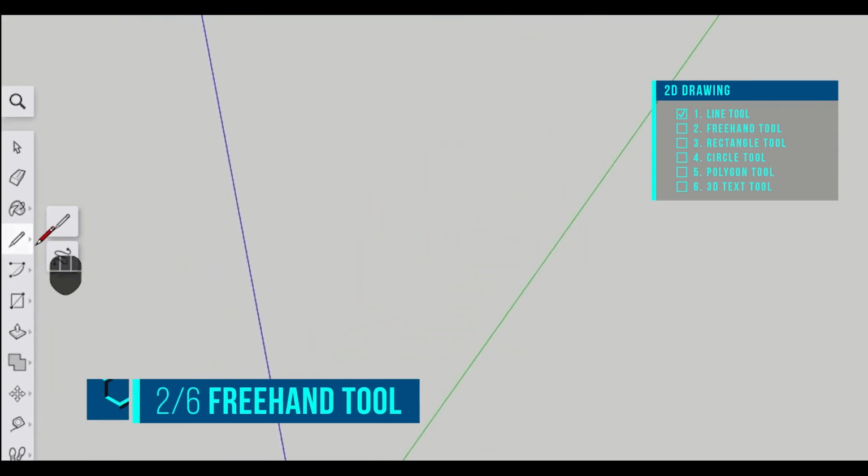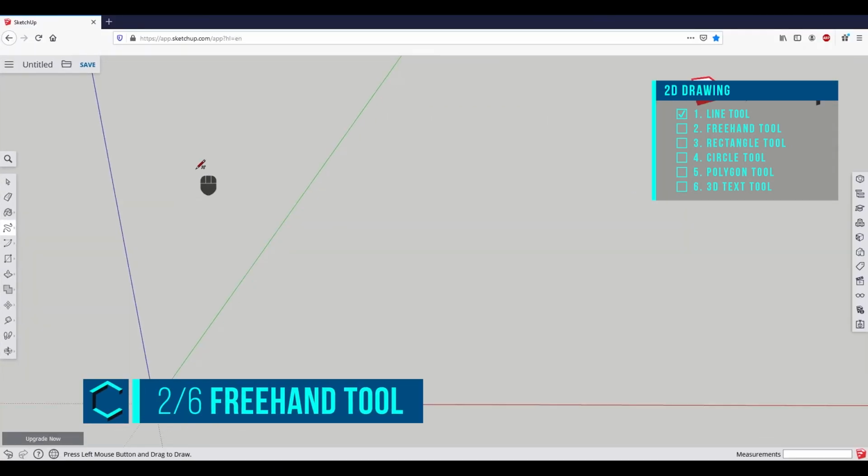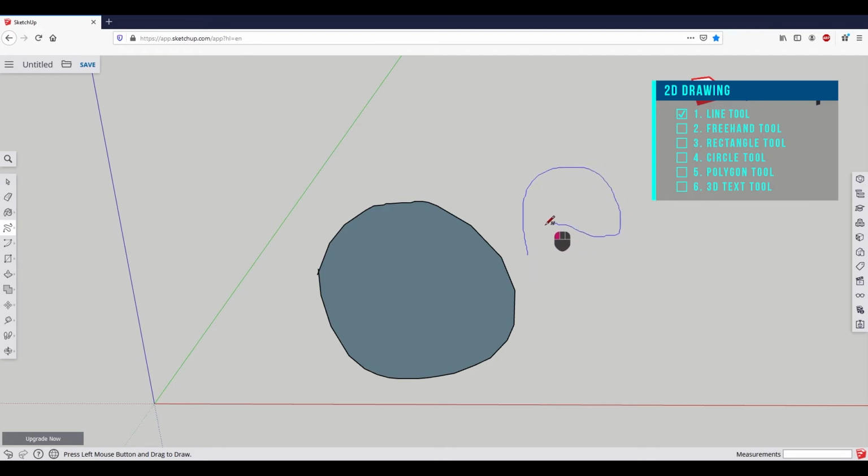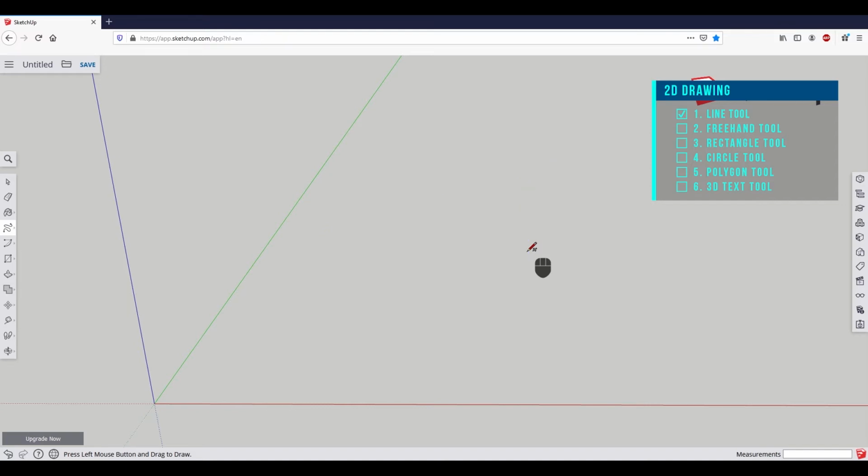Now select the freehand tool from the toolbar, click and hold left mouse button and move the mouse to create the drawing. As soon as we close the outer shape and release the left mouse button, the surface will be filled. But you can tell from the outer edge that the tool is very inaccurate, so it's actually not used very often. But for the beginning, you can practice it a bit. When you are done, press Ctrl and A and delete the sketch.